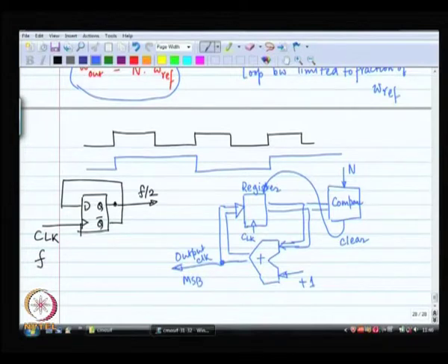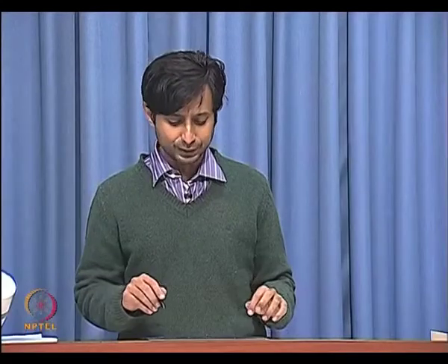Okay. It is just that this is not how it is done because of speed and other reasons. So, finally, this is not the implementation that we use, however, this is a crude possible circuit, right. You could use an adder whenever the result reaches n, you clear it, take the output from the MSB, right. That will successfully divide your input clock by a factor n.